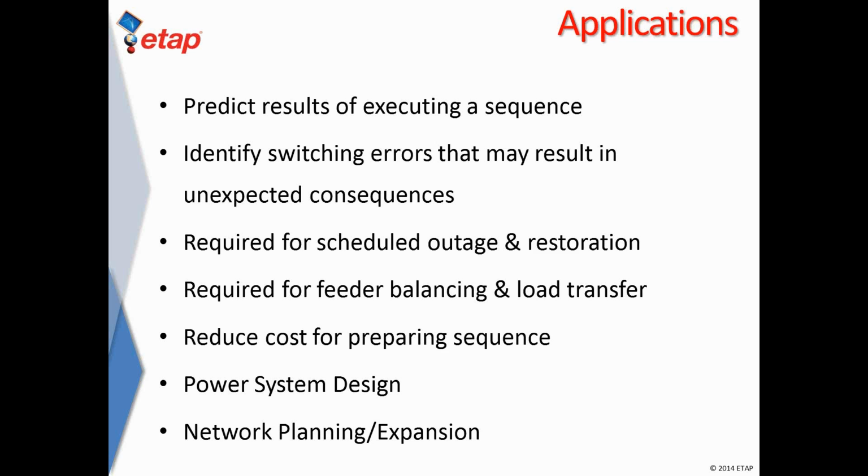It is used when performing scheduled outages and restoration sequences, right? Feeder balancing and load transfer. It's also used to check perhaps existing switching sequence procedures and trying to figure out or reduce cost and losses.